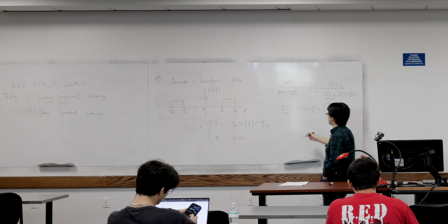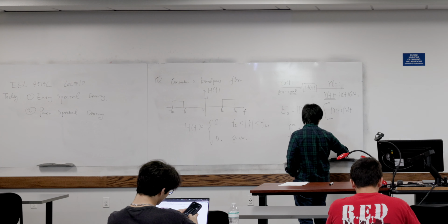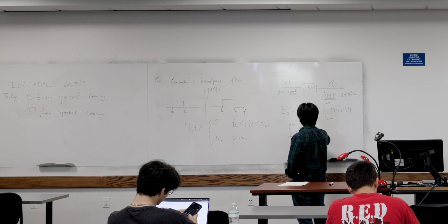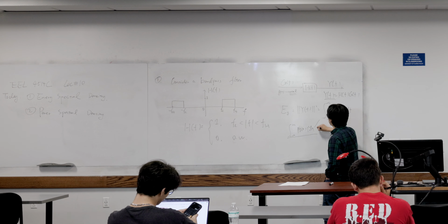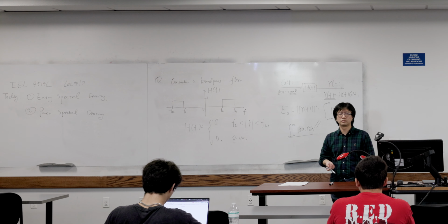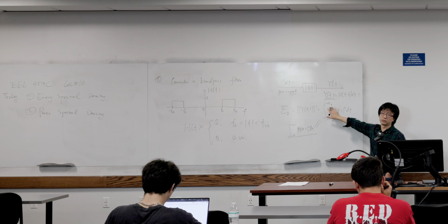So basically what we do is compute the energy in time, which is not g(t), but y(t) squared dt, right? So this is the definition of the energy of the signal. This is equal to that. Why is it equal to that? Because of the Parseval theorem. Whatever we compute in time is equal to whatever exists in frequency.